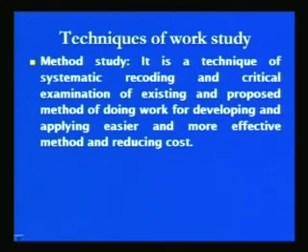So, basically method study targets the recording of the different events which are being carried out in the existing method, analyzing them and examining them critically, so that the avenues for improvement can be identified so as to develop the most efficient, effective method in such a way that it can be applied easily, and it helps to reduce the cost and the operator's fatigue also.